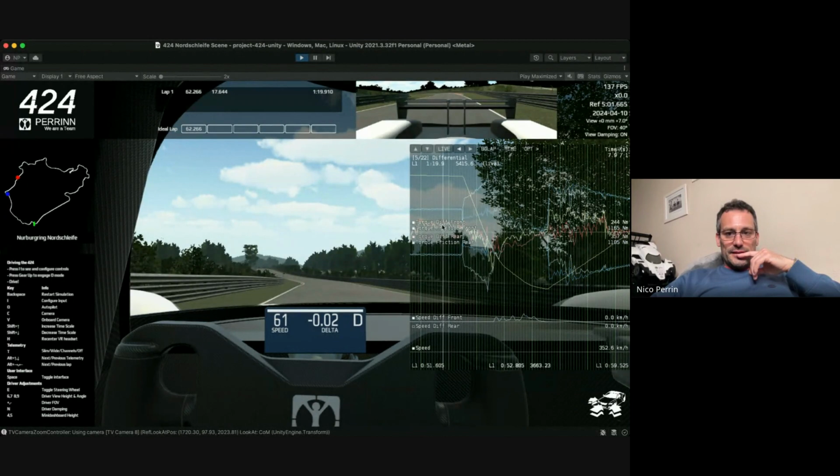And the torque is coming from the regenerative braking, and that torque is going to the ramp system and is locking the diff. As you release the brakes and the regen goes off, the diff starts to open, and now you allow one wheel to move relative to another. But when you go on throttle, the ramp is quite aggressive, and we are locking the diff straight away.